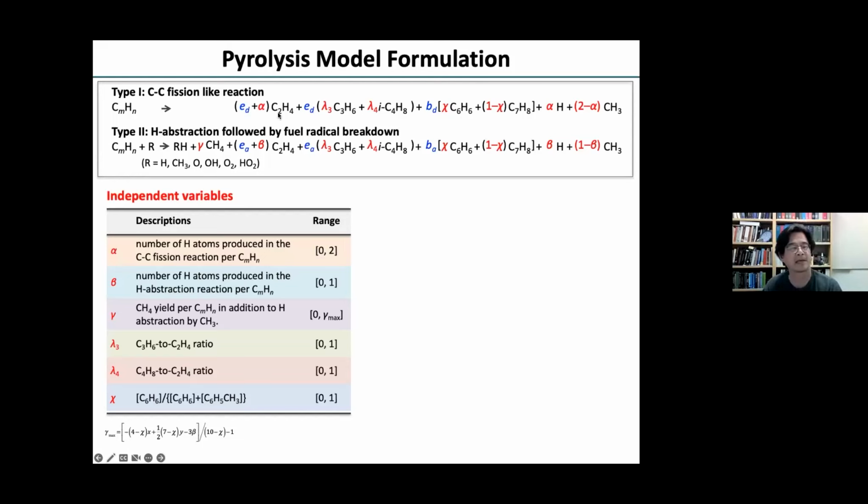And you can massage the lump reaction process into something that looks like what I'm showing here. All the Greek letters marked in red are properties, parameter values that we need to determine. The blue English letters, ED and BD, EA, and so on, are dependent variables. These values depend on the Greek letters, the alpha, the beta, the lambda, the chi, and so on.